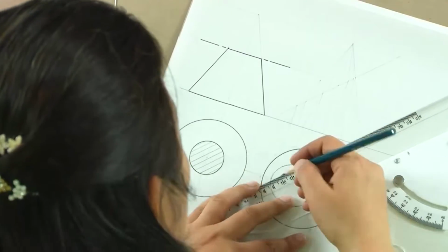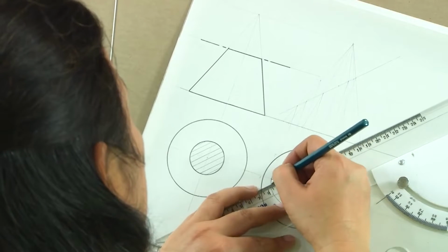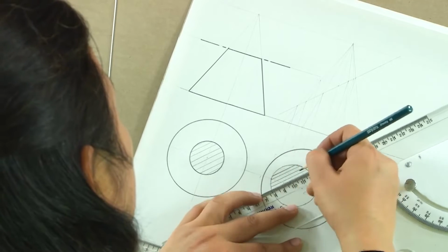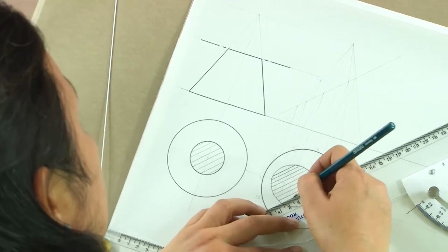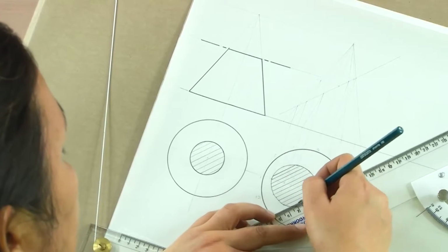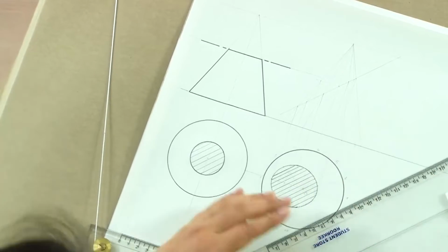The base of the cone remains intact. And the central portion which you have here is actually the section. So we will just hatch this portion which represents the section of the cone, and it is the distorted ellipse. It is not the true shape of the section because we are not seeing parallel to the section.